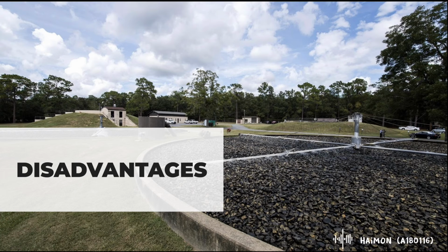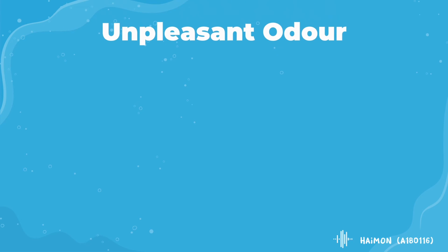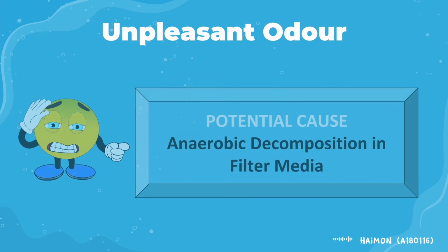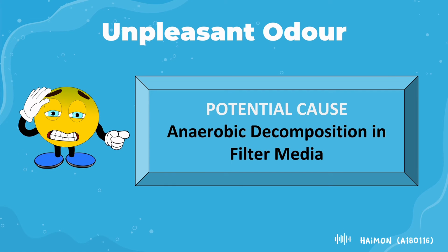Hi, I'm back. Now, it's time to know some of the disadvantages of the trickling filter. Unpleasant odor is one of the undeniable risks from trickling filters. One of the potential causes of this problem is the process of anaerobic decomposition in filter media due to excessive organic load.